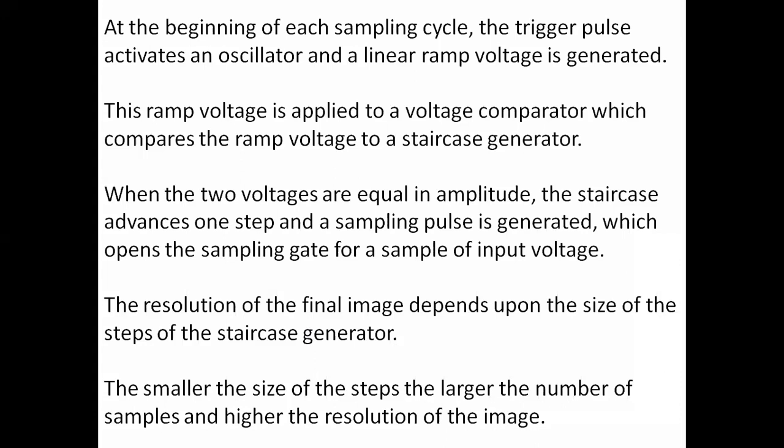If the amplitude of the staircase signal steps is very high, then we cannot sample continuously. There will be a large distance from one sample to another sample, and due to that we cannot construct the proper shape of the input waveform. So that is explained here.